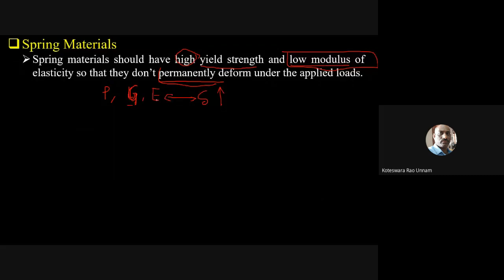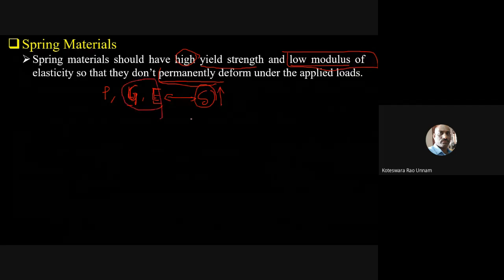Or I can say that if E is more, the stiffness is more. If the stiffness is high, then deflection will be low. But if you take the reverse, that is low modulus, in the sense deflection is going to be high. Therefore, it will satisfy the condition.